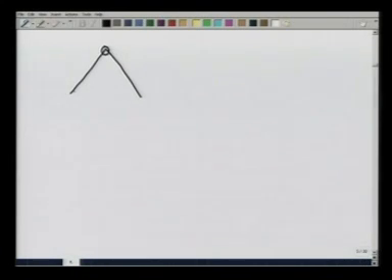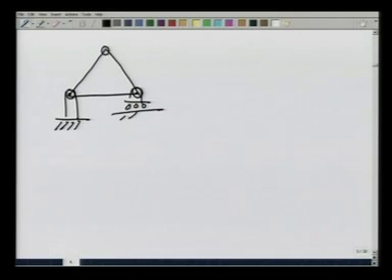For completeness, I should point out that the triangle that we just made should actually be fixed like this on a fixed pin on the left and on a roller or wheel on the right. This will make the system statically determinate. Through this, what I have done is provided you an example of solving for the forces in a truss through the method of joints. That is, we take each joint, each pin at each joint to be in equilibrium.